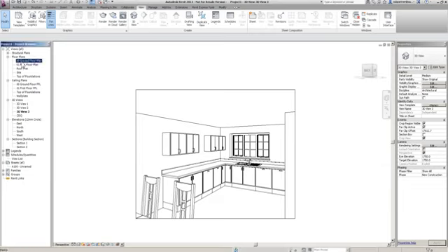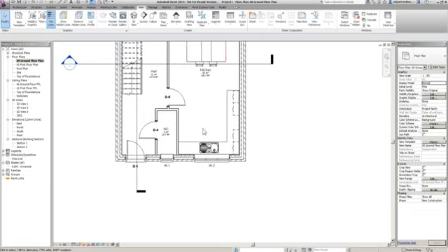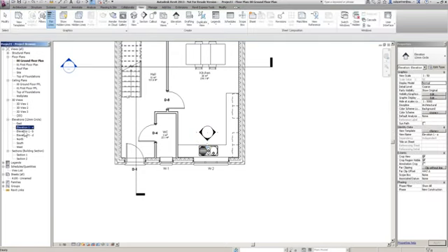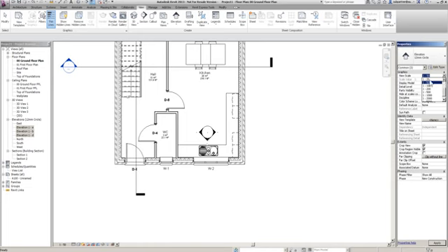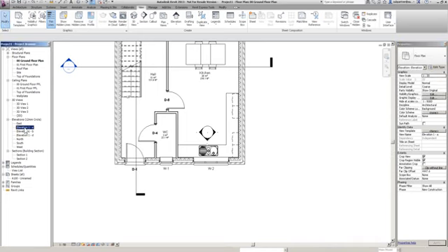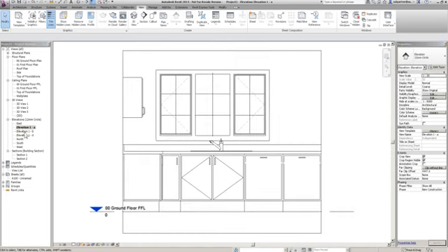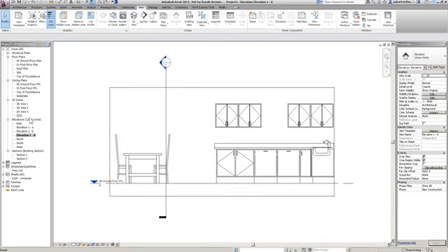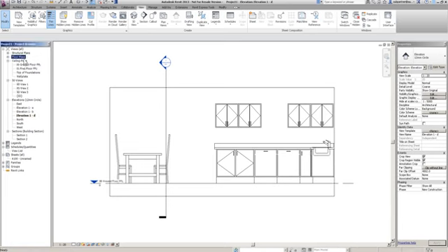What we can do, something I like to do, is throw a little room elevation in here. We've all done elevations, room elevations for tiling layouts, etc. in kitchens. Okay, I'm just going to click there, turn that elevation on as well. You can see it's making elevations in here like so. I'm going to make these elevations 1 to 20s. Fantastic. When I go into them, as you can see, we've basically got my room elevations for my kitchen. So you can start to put your tiling layouts on, all of that kind of stuff, really nice and quick. Okay, where are we at? Let's just have a look.